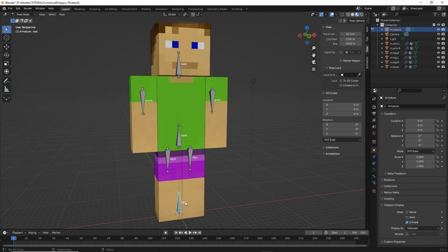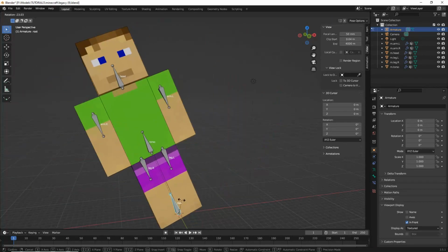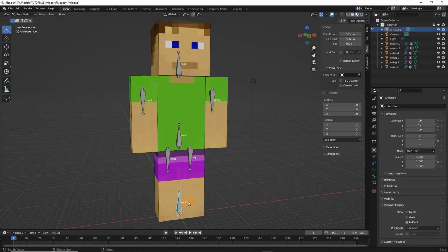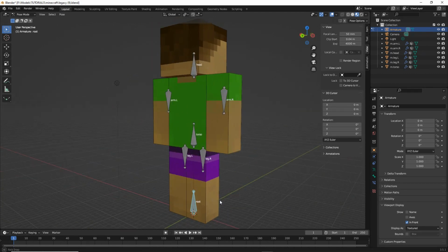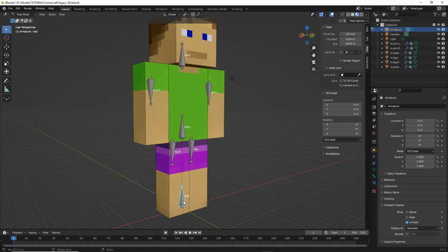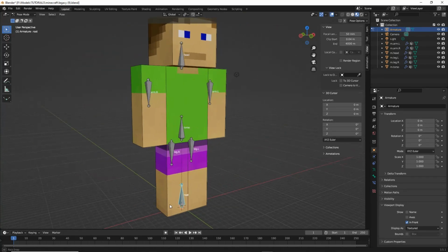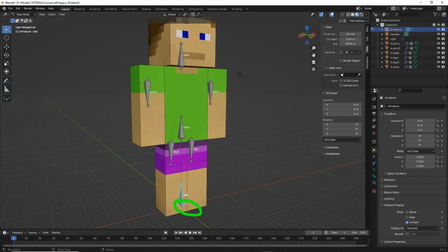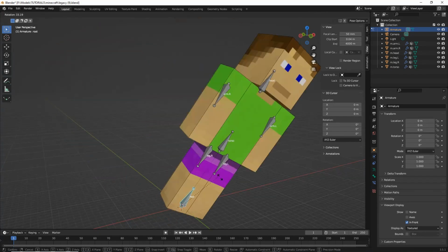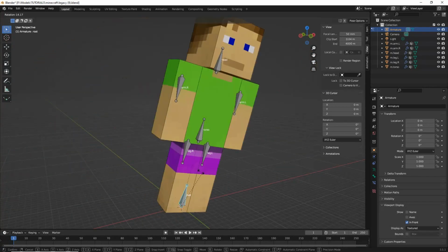Similarly for the root bone, which actually we want to do that because that controls the entire character. So if the animation has the character moving off grid, whatever the character is being moved for contextually, generally you wouldn't do it by manipulating the root bone, you would do it programmatically inside the game. The root bone doesn't move, but it gives us control over the entire avatar.